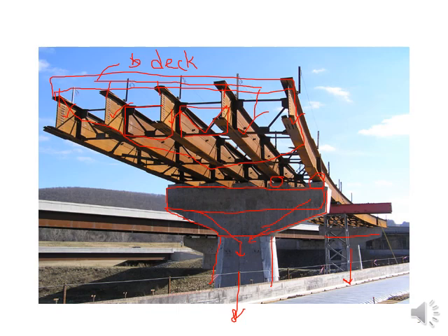Here you can see that there are no floor beams actually. Either your stringers are placed directly on abutments on both sides without intermediate columns or piers, or, if the spans are longer for the steel girder bridge, you have to place piers intermediately. So your longitudinal steel girders are placed either on the piers or directly on the abutment.